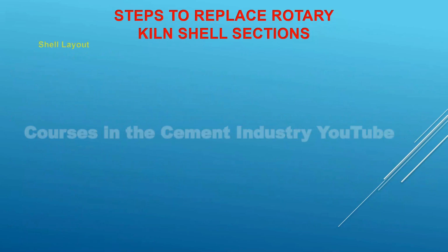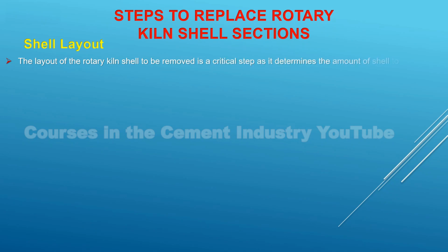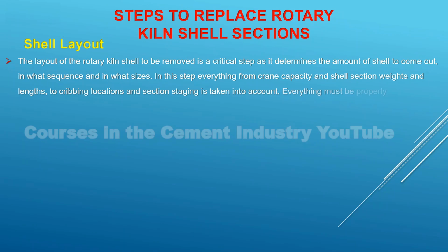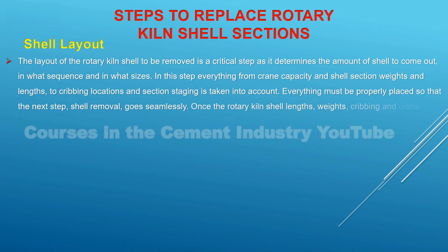1. Shell layout. The layout of the rotary kiln shell to be removed is a critical step, as it determines the amount of shell to come out, in what sequence and in what sizes. In this step, everything from crane capacity and shell section weights and lengths to cribbing locations and section staging is taken into account. Everything must be properly placed so that the next step, shell removal, goes seamlessly.